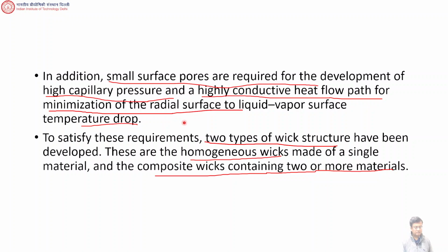So we'll understand this because today is the introductory lecture on heat pipes. Today I obviously didn't have much time, but this is important to our understanding: if you have small surface pores, then the capillary pressure difference that you create will be higher. We don't understand it now, but we'll do some simple analysis. Actually, when it comes to heat sinks and heat exchangers, we took a more applied approach.